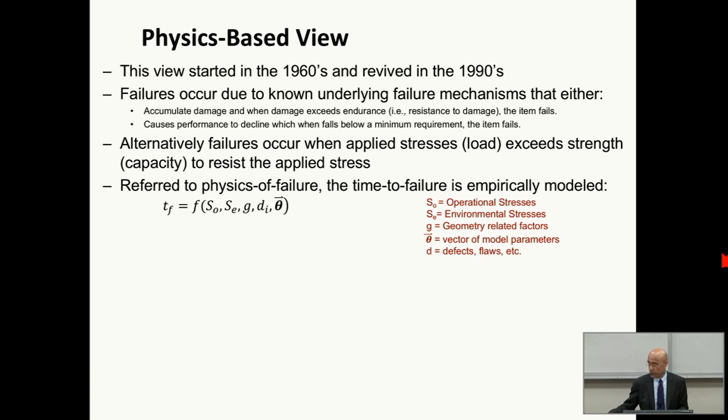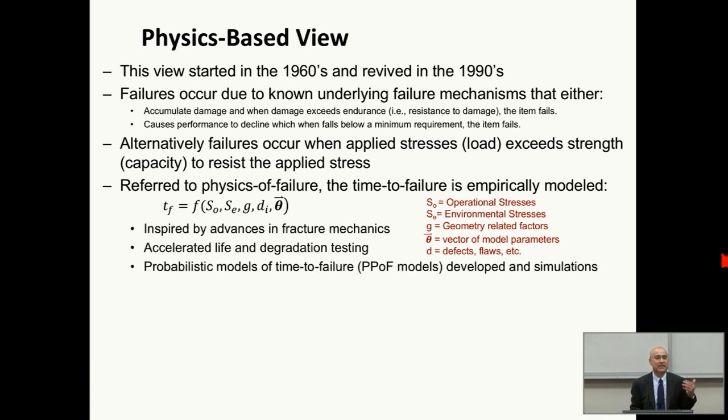They need to be developed, of course, for every failure mechanism separately. These kinds of techniques were originally inspired by fracture mechanics, and the way we develop them most often relies on the concept of accelerated life or degradation testing, whereby we fail components by applying these stresses at a much higher rate than normally operated in use, causing them to fail in a faster time.